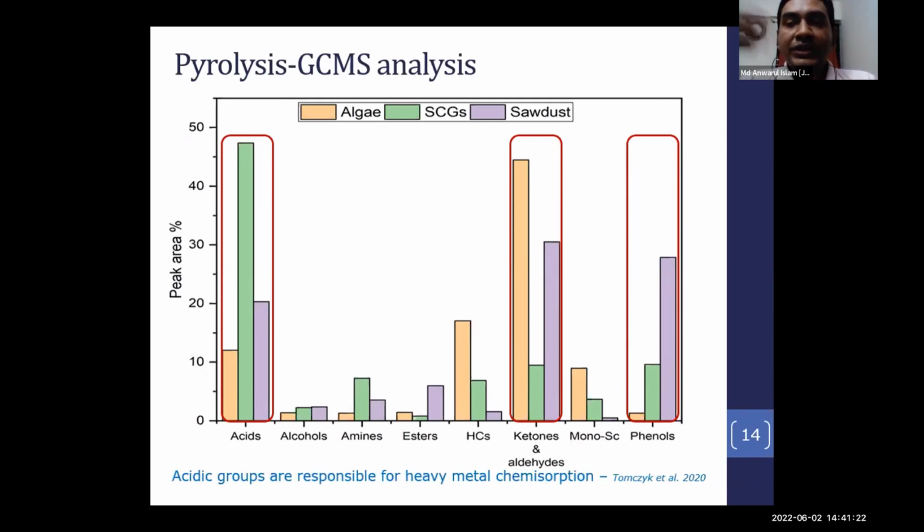So two things we can understand here. The pyrolysis vapor shows us the remaining chemical compounds which may remain on the biochar surface and give us some acidic functional groups, which will help us to adsorb the silver species. And secondly, the high acid value or high molecular weight compounds in the pyrolysis vapor can be condensed to produce bio-oil, which can offset our pyrolysis cost.